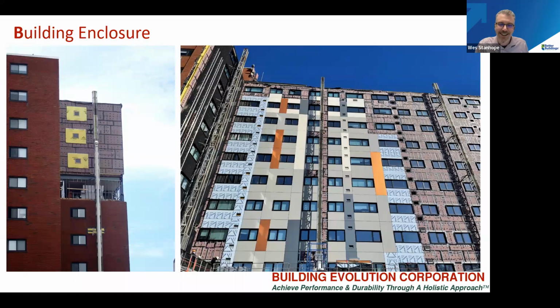This is a project where it tackled the actual enclosure during the actual heat pump upgrade. This one did a ventilation and heat pump upgrade and took the actual brickwork down. There was a reason why the brickwork had to come down, but it also did a deep energy retrofit to tackle the enclosure to take down the thermal load on the building and improve the air barrier, and to add ERV ventilation and heat pump for heating and cooling within the building.